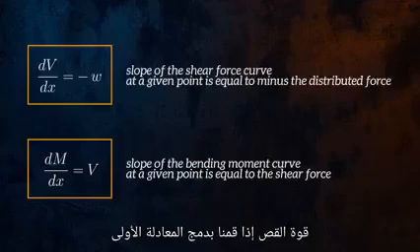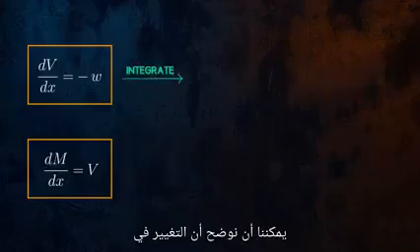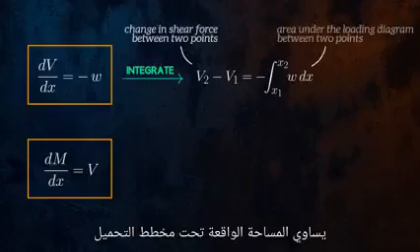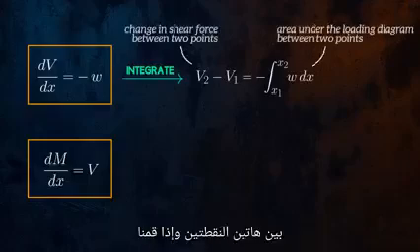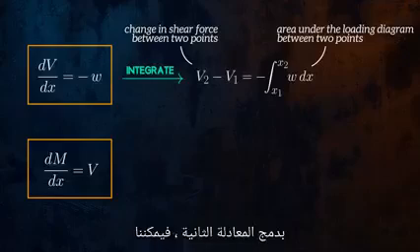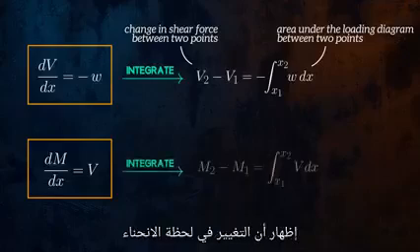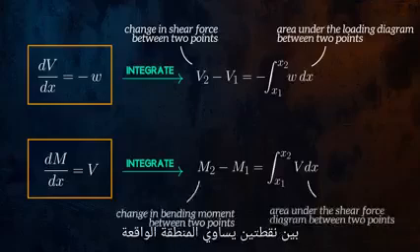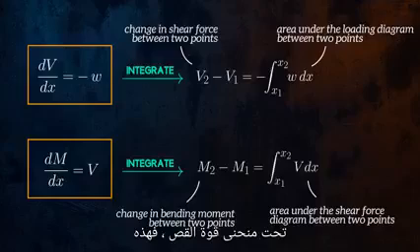If we integrate the first equation, we can show that the change in shear force between 2 points is equal to the area under the loading diagram between those 2 points. And if we integrate the second equation, we can show that the change in bending moment between 2 points is equal to the area under the shear force curve.